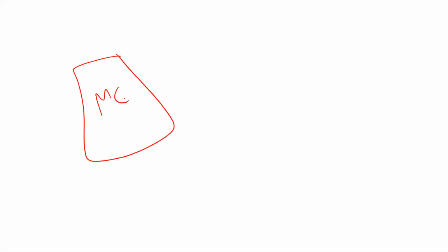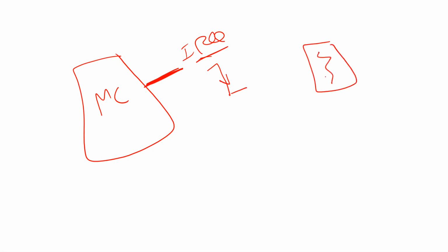Look here, guys. If this is a microcontroller, and we have one pin here, for example, when you had IRQ. What is IRQ? Very simple. IRQ means every time there is a falling edge, I want to trigger an interrupt and execute a subroutine. That's what IRQ means, right? Okay. Now, I want to make an analogy between IRQ and input capture. You will be surprised. You will find there is overlap between IRQ and input capture, right?